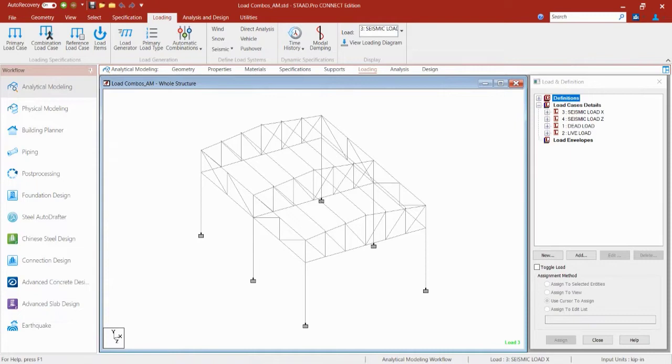This would be a load combination, which is a set of results which are combined algebraically to produce superimposed sets of results processing. Now, a traditional load combination would be completely appropriate for something like a linear elastic analysis, but it would not be appropriate for any type of second order analysis. I like to make sure that that is perfectly clear, because if you need to capture second order moments and effects on your structure, you definitely need to go with the repeat load case. So I'm going to show you the difference.